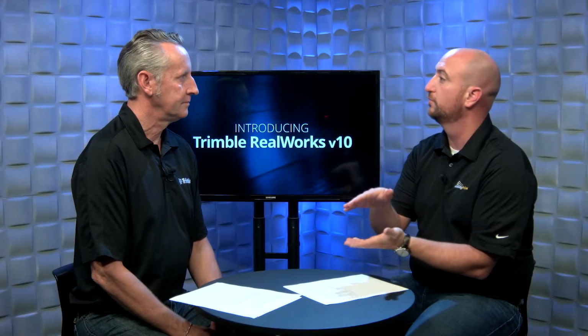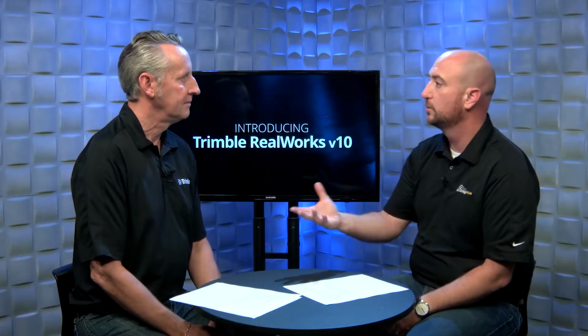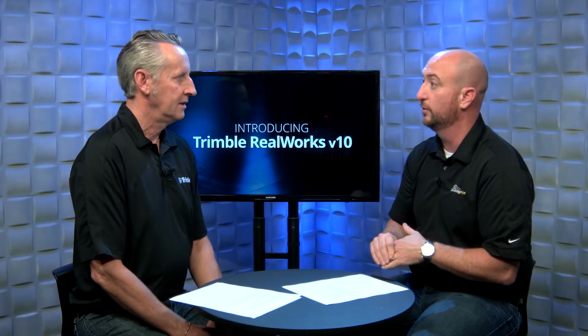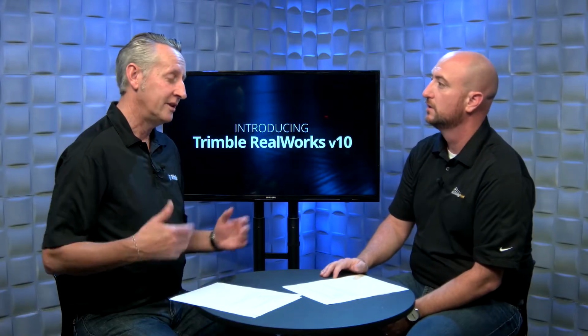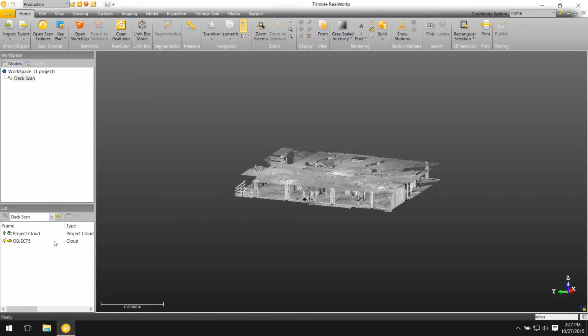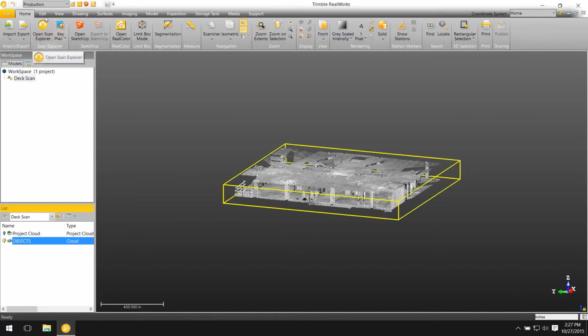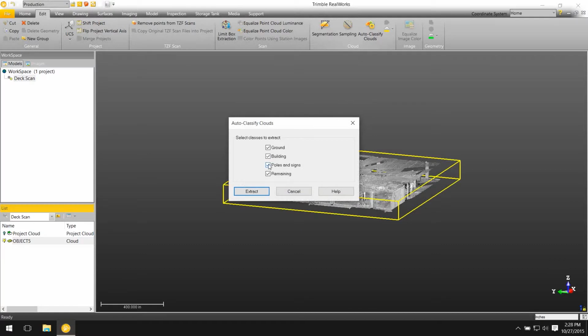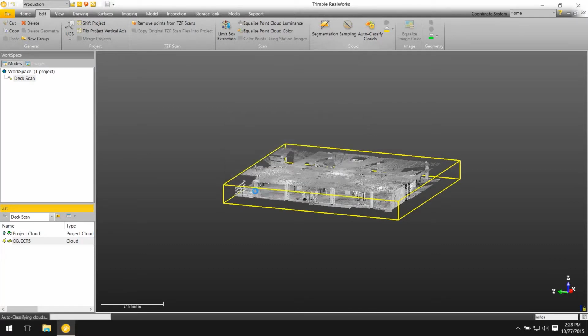Okay, so let's talk a couple of specifics as far as workflows or features in the application. Could you give us a couple examples of what users are now seeing in Realworks that are new and changing the way we do things? Yeah, I think one very exciting feature that they're going to see is this point cloud classification. What it does is, just with a click of the button, it will separate out the point cloud into different features. So one of those being ground extraction. In the past, we were talking before where it was very much a manual process. Today, that is extracted out automatically.